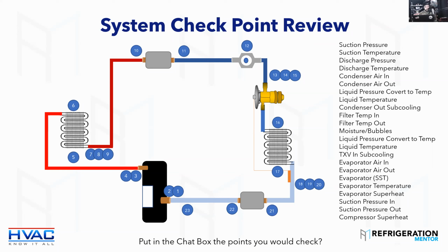Someone's asking me, do I find that it shrinks after time? I haven't found that it shrinks. I find that it is harder to glue and put together than the regular Armaflex, and you do got to take a little bit of time, and it's harder to bend because it's got that jacket on it. But if you're looking to replace the Armaflex with something, I highly recommend it because it's really good stuff.